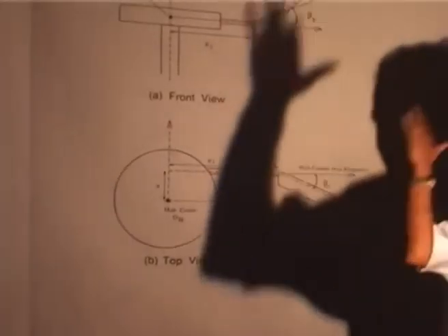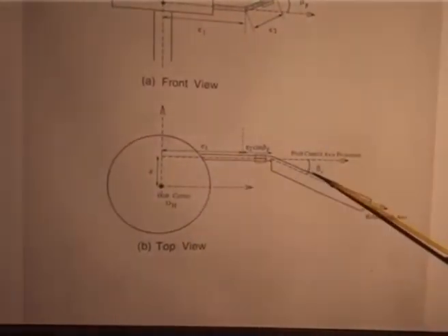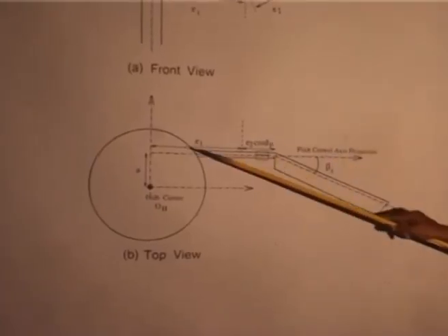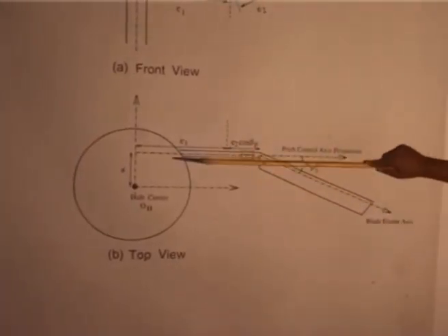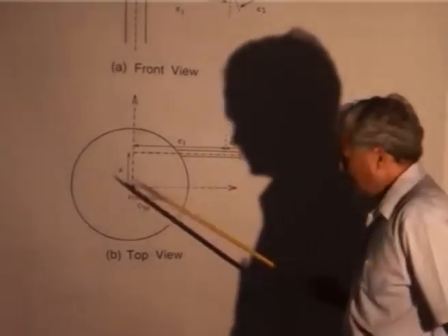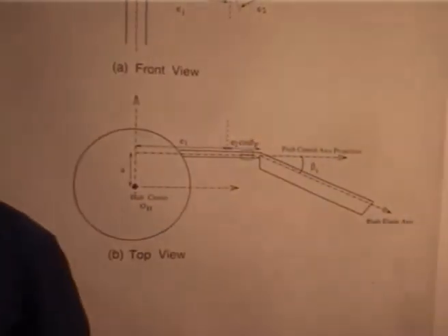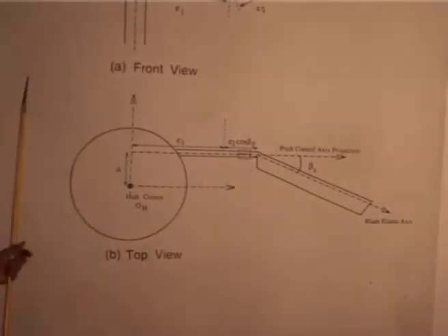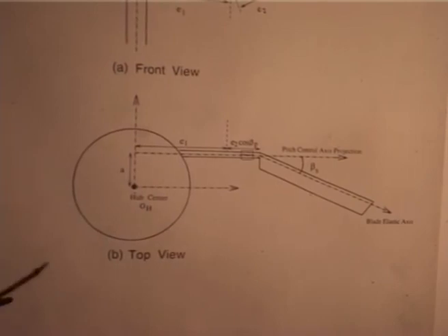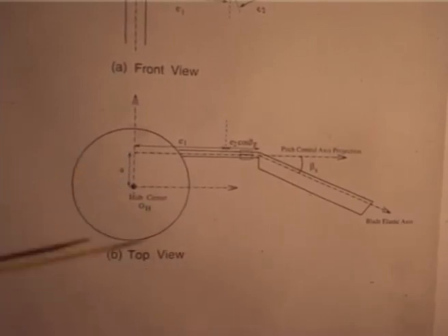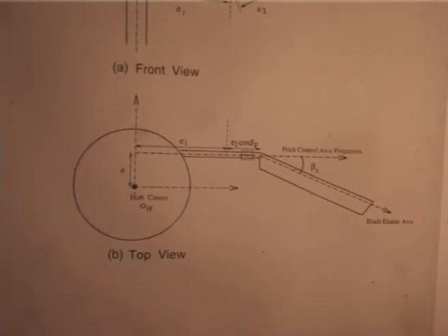Now, the next, if you view from the top, of course, this is just the pre-sweep I have mentioned. You see the axis of the blade need not pass through the center of the hub. It is not that the blade is attached here, it can be attached, but it can also be offset by some small distance.